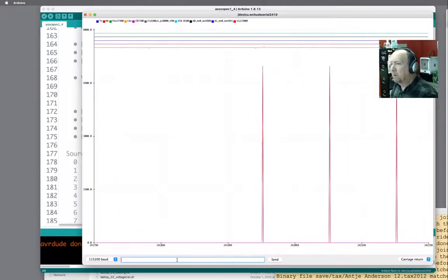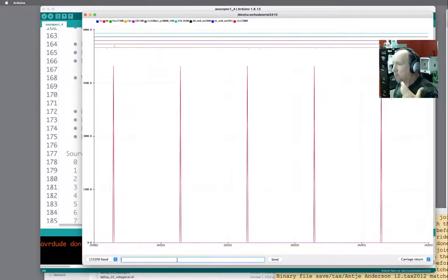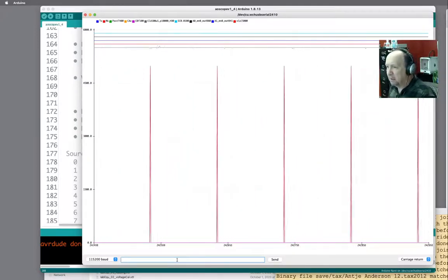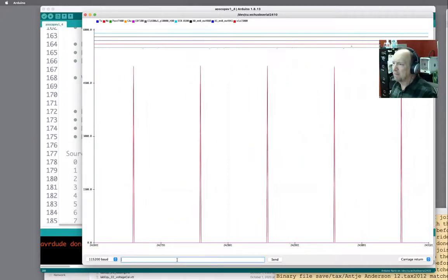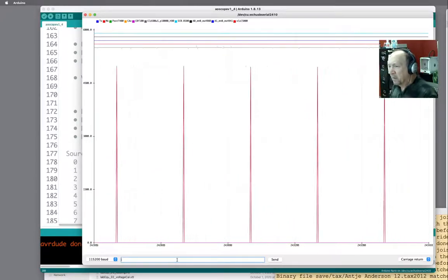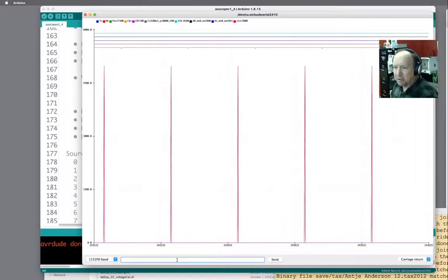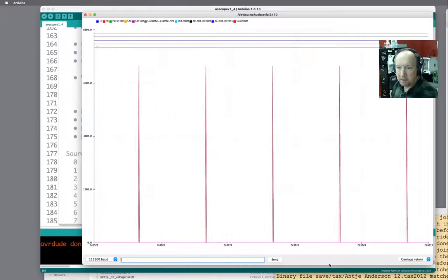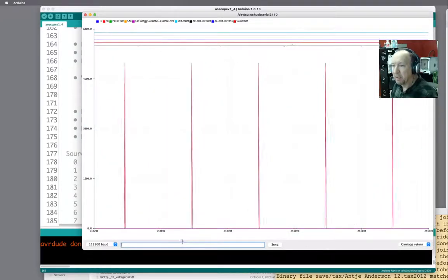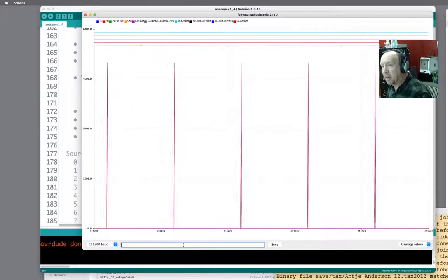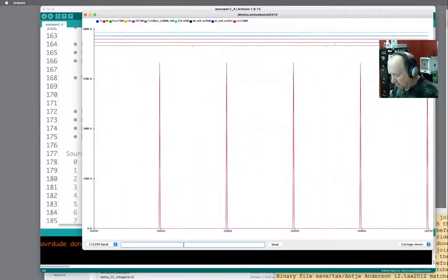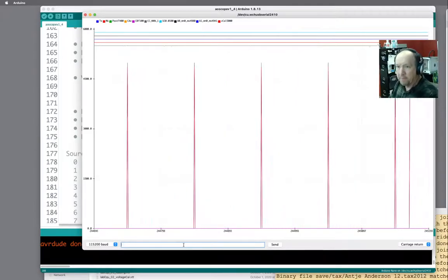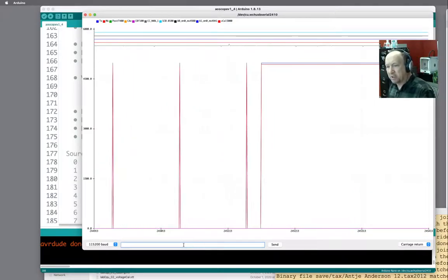Now, the clock is still giving us that 1 second tick that's only 90 counts or 9 milliseconds in length. So that gives us a spike that we're seeing right now. So if I want a logic output instead, let me bring this up just a little. Okay, if I want a logic output instead, I can come in here and just say I want to be logic high, L H, and hit return. And you can see the output signal just goes high.